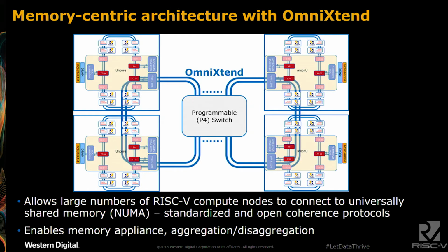And today, this is just TileLink over Ethernet, right? So we're using Ethernet L1 as the underlying fabric, and then we're sending TileLink traffic over this. And the idea is that you can connect boards directly. And you can see this live today in our booth downstairs. There's a demo on FPGAs. But there are these programmable switches now in the Ethernet world where you can remove Ethernet L2 and replace it with your own sort of L2 protocol. And we do exactly that with the TileLink protocol.